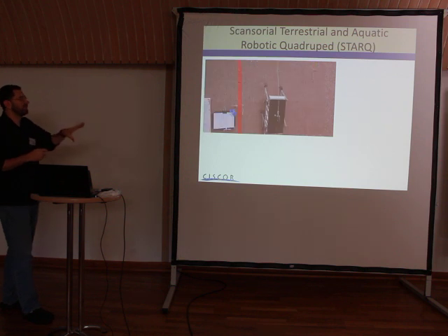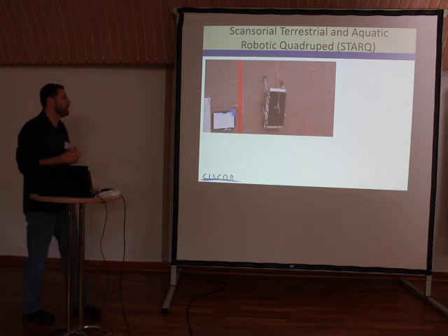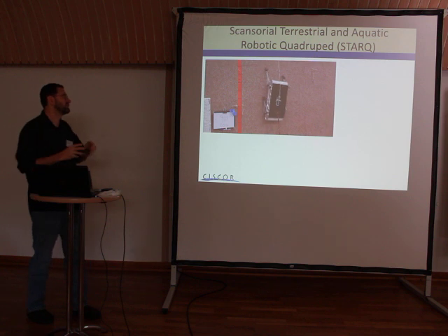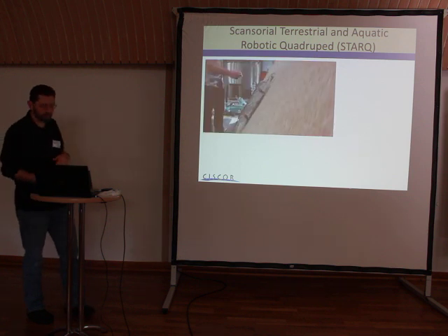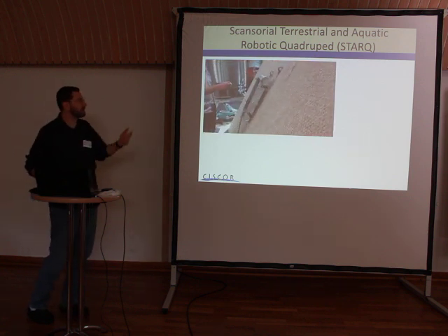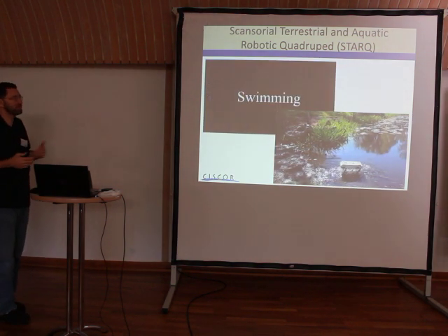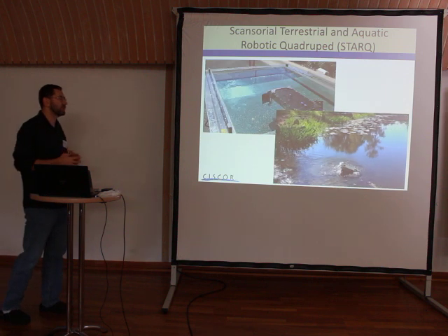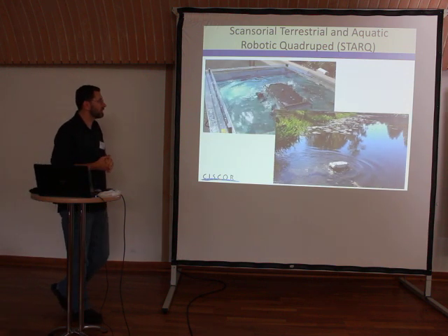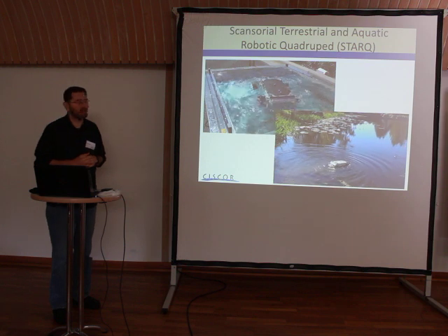Turns out that this type of leg morphology works better than the RR or other types of 5-bar leg linkages for climbing. Here we are on purely vertical terrains. In addition to climbing on vertical terrains, we can also move through the fluids, and so you see here a video of it transitioning from walking on the ground into the aquatic mode, and you can see some sample swimming in our little baby tank outside of our lab above.